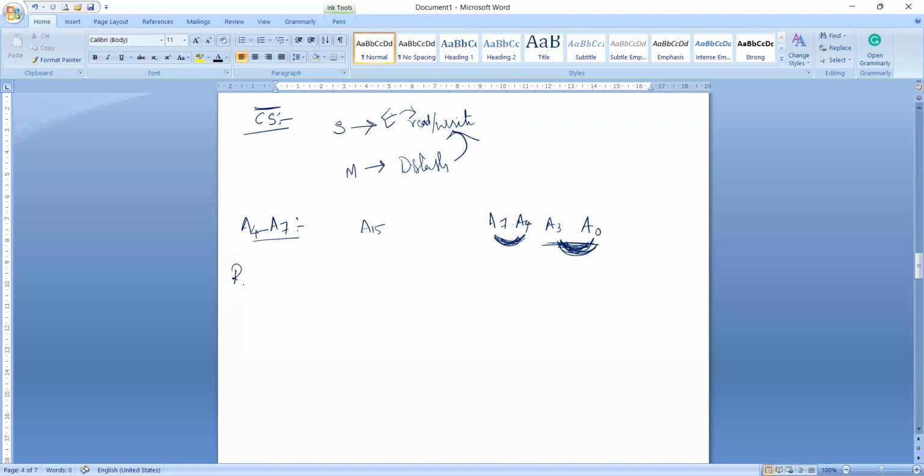And next one is the ready signal. This ready signal is an active high asynchronous input signal which makes the DMA ready by inserting a wait state. And next one is the HRQ pin. This signal is used to send the hold request. In slave mode, it is connected with the DRQ input line of 8257, whereas in master mode, it is connected with the hold input of the CPU.